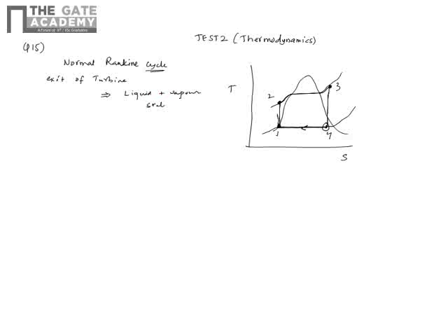Because the dryness fraction is less than 1, this liquid is not desirable, because these liquid droplets will try to damage your blade surface.